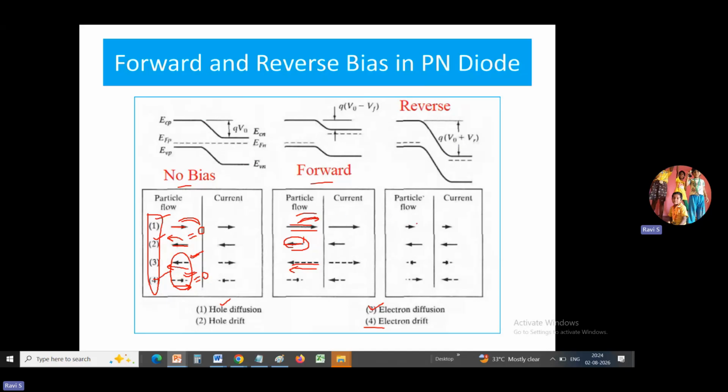In the same way, if we observe the reverse bias case, the amount of charge carriers crossing the junction is very small when compared to charge carriers drifting. So here, when compared to diffusion, the amount of drift current due to holes is large. So even in reverse bias, current flows due to the drifting mechanism. From this, we can conclude that under forward bias, the diffusion carrier transport mechanism dominates, while under reverse bias, the drift current carrying mechanism dominates.